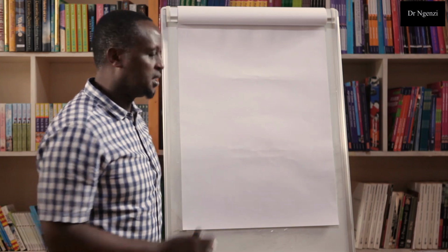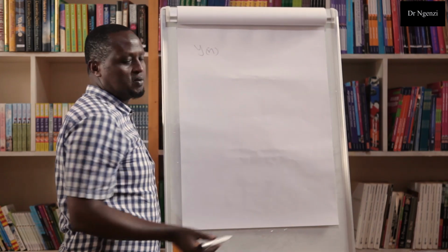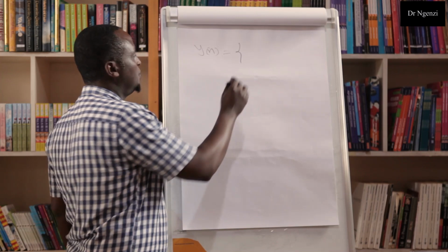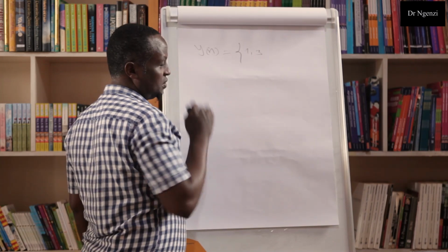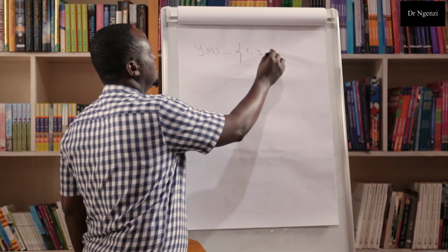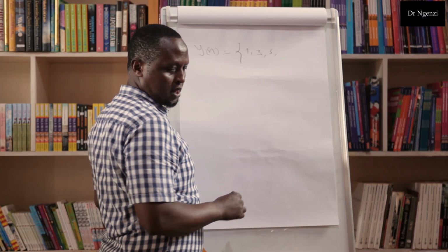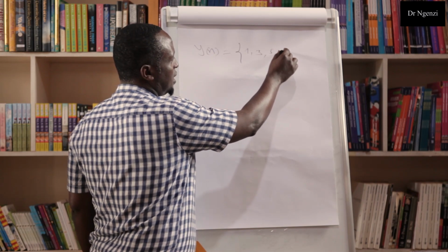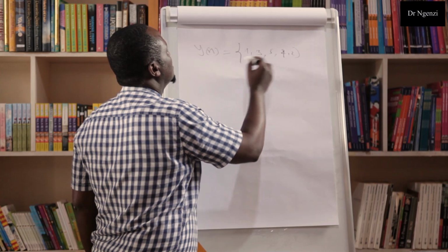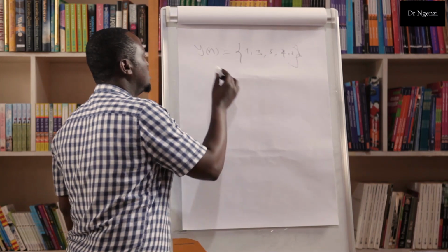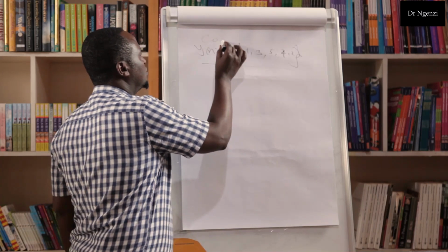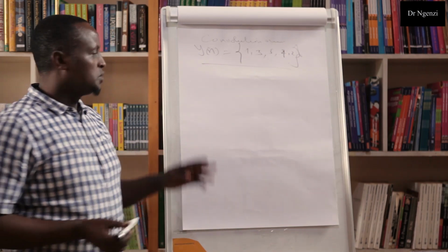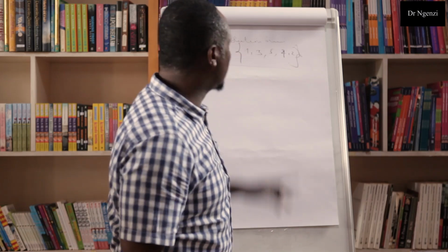So you will have your answer as y. From that sequence method, you will have your answer as these values. For example, 1, 3. At n is equal to 1, at n is equal to 2, it will be 3. At n is equal to 3, it will be 5. At n is equal to 4, like that. So it will be in this way. So this is the answer after the convolution sum. But also you can use what we call the tabular method. That was the sequential method.